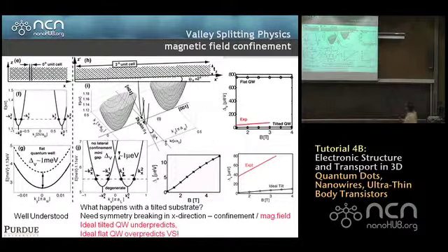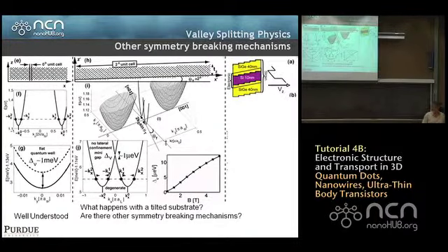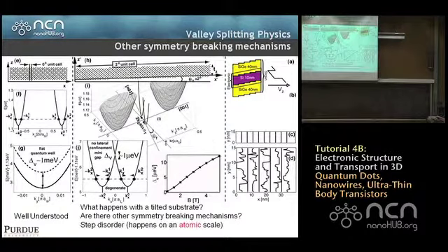And the question now is, how can we reconcile this? So here's a flat quantum well, too large, a tilted quantum well, too low. It doesn't match experiment. So there's something else, right? So here's this tilted quantum well, and we can do a couple of things, right? Number one, we can say, well, these steps are not perfect steps. They're actually rugged. Okay? Also, surrounding the silicon is really silicon germanium.